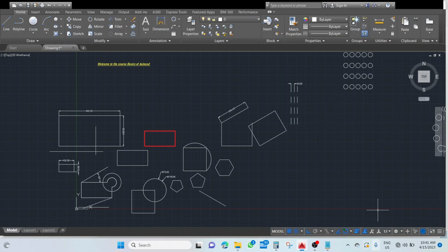So here now you will find out the line weight, so you can turn the line weight on or off. Here I can change the thickness of a line. Next, I have to change the type of the line. So here I can change the type of the line. Go into the other. When you go into the other, I have to load the different lines.